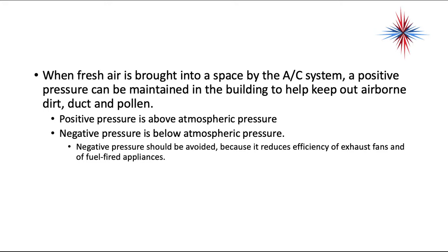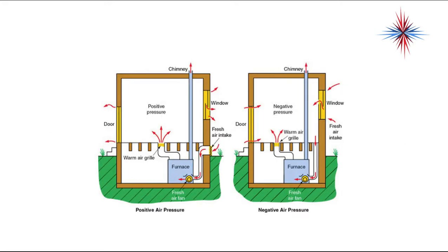Negative pressure should always be avoided in a building because it reduces the efficiency of exhaust fans and exhaust from fuel-fired appliances. We want to avoid negative pressures at all costs. Always want to keep things at a positive pressure. Two examples of this, okay?